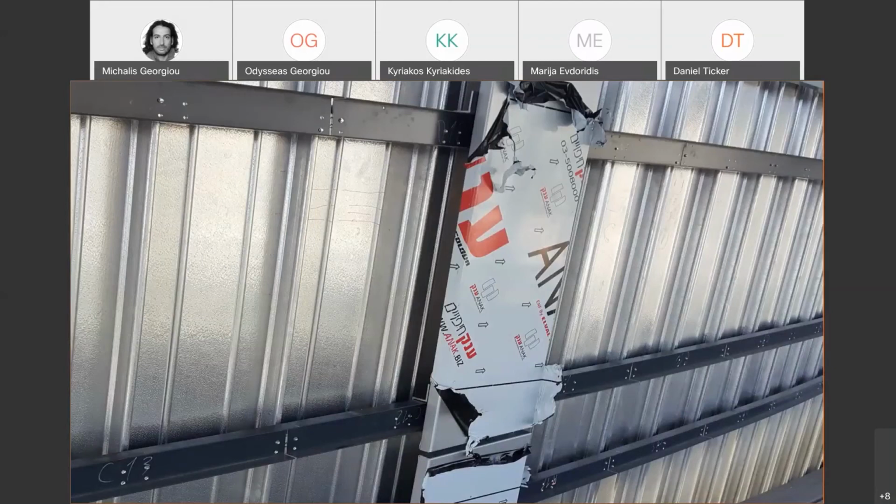Since we've encountered all those setting out issues and difficulties and the visibility issues through the scaffolding, we said that the easiest way to do this is to place horizontal supports that will be parallel to the XY plane, which could be placed in a very traditional manner. All the contractors knew how to place horizontal fittings, and then digitally fabricate all the panels in order to have horizontal fittings and be hung horizontal. So it's a combination of a traditional setting out method and digital fabrication.